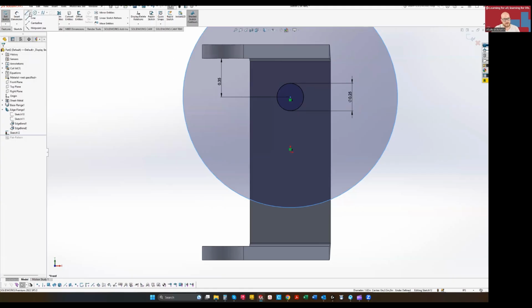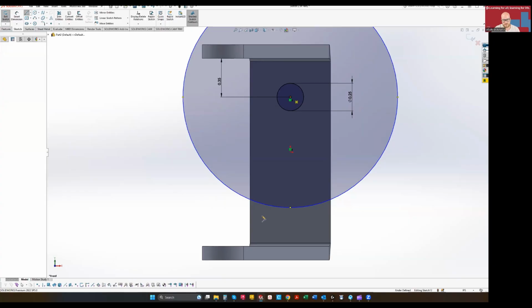Now let's use our line tool, create a center line from the center of this circle here out to the perimeter of the circle that we just drew, which, by the way, also has its center point at the center of this fully defined circle here. Now let's grab another center line, just like this. And we're going to make those two lines equal.